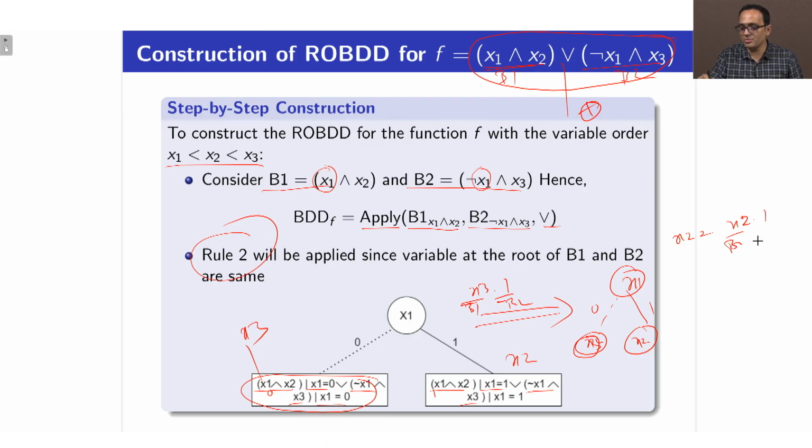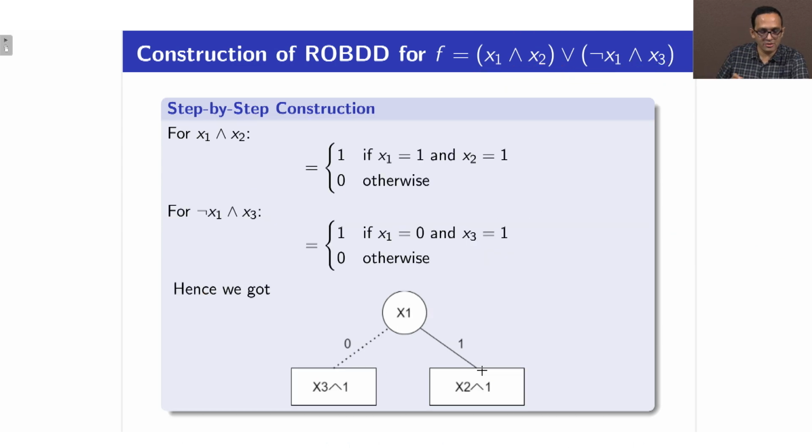So, this is my BDD B2, this is my B3, and the operator is AND, right, and I can apply the same rule. So, what rule will be applicable here? The root node is x3, here this is 1. So, rule 3 will be applicable, right. With this rule 3 I can combine again to get the resultant BDD, and I can combine repeatedly on both sides and get the BDD, just for completeness. So, what I did, I get this, right. This is the BDD I got.